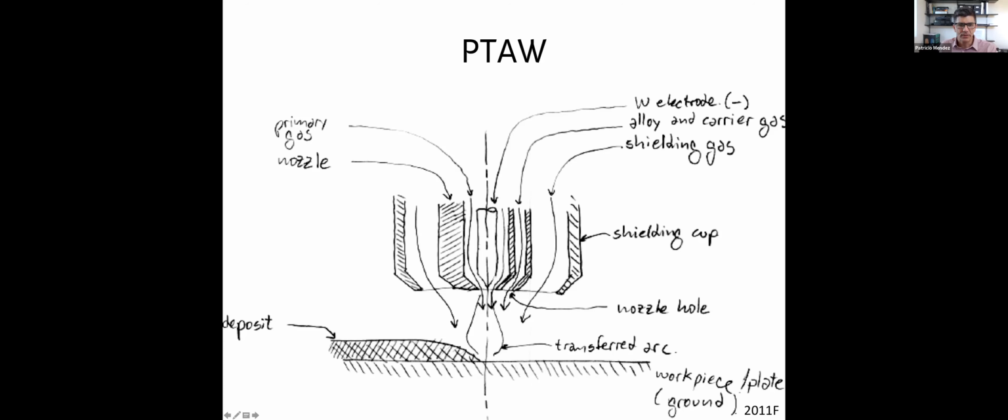There's another important difference. In laser cladding, the laser tends to be quite far back from the weld, because it's just light being projected as long as you get the focus somewhere around the weld pool. In PTA, because you have an arc, you're forced to have a given arc length that would work with the system. So in this case, your torch has to be quite close to the component. But yes, similar to laser cladding, you can do additive manufacturing with PTA too.